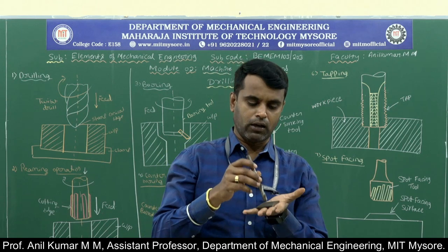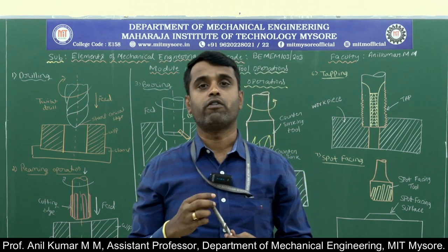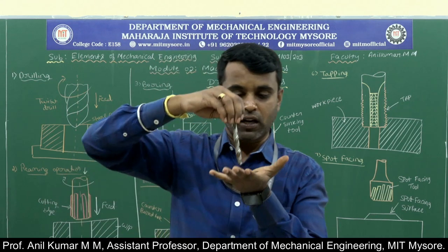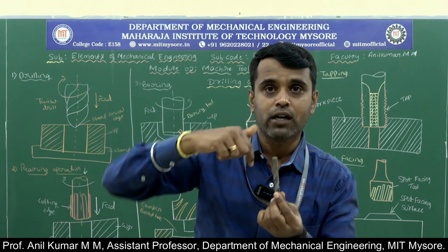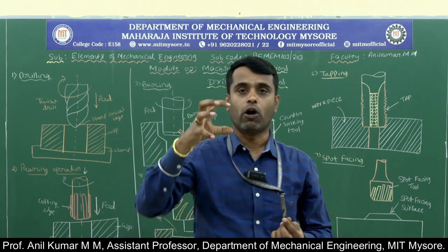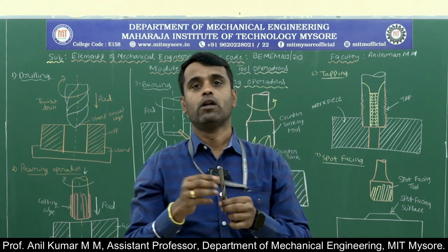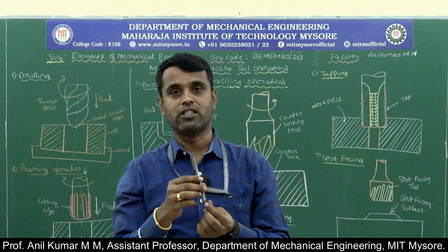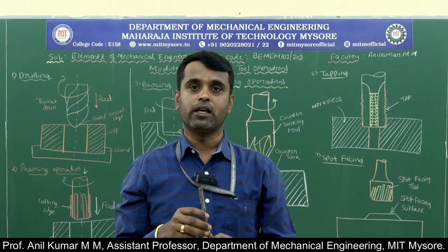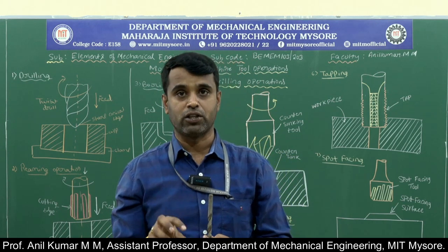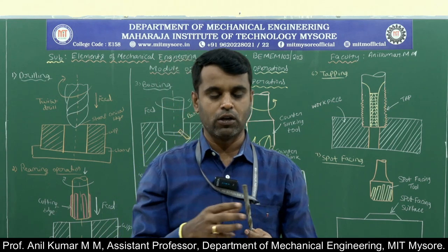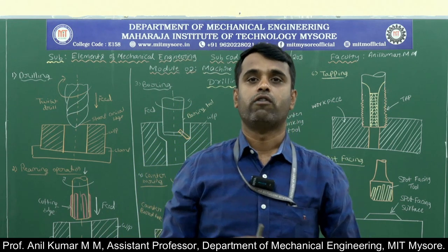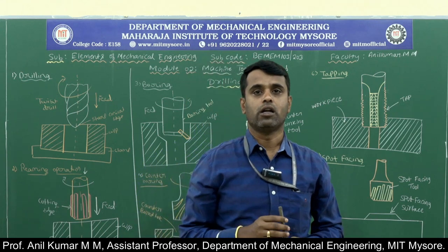During the drilling operation, a large amount of heat is generated, because the cutting action takes place inside the workpiece material. In order to cool the cutting tool, we continuously supply coolant. The coolant reduces the heat generated during machining and reduces friction, and that produces a better surface finish for the hole. That is the drilling operation.